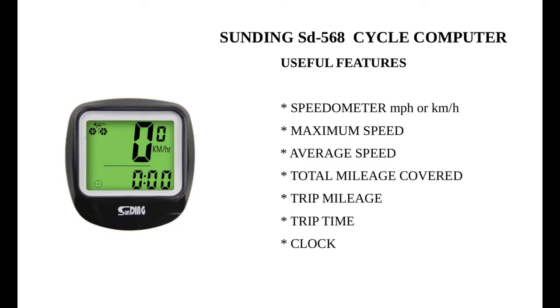The encoder has differential RS422 outputs, but I used it single-ended. The 1 pulse per rev logic signal is high for 90 degrees of encoder rotation, that's 25%. It can easily drive an opto-isolator via a 1K resistor, and the cycle computer works OK with this longer length of pulse. It was simply a matter of cutting the cable and interfacing it via the opto-isolator.